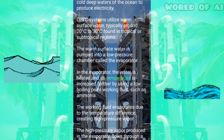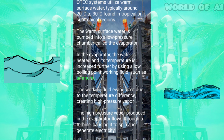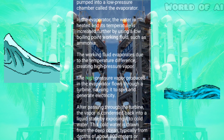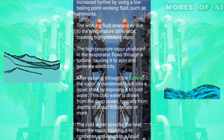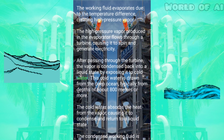In the evaporator, the water is heated and its temperature is increased further by using a low boiling point working fluid, such as ammonia. The working fluid evaporates due to the temperature difference, creating high-pressure vapor. The high-pressure vapor produced in the evaporator flows through a turbine, causing it to spin and generate electricity. After passing through the turbine, the vapor is condensed back into a liquid state by exposing it to cold water.